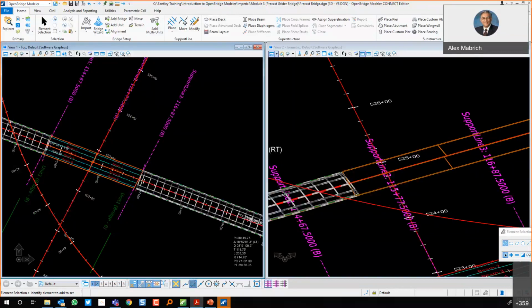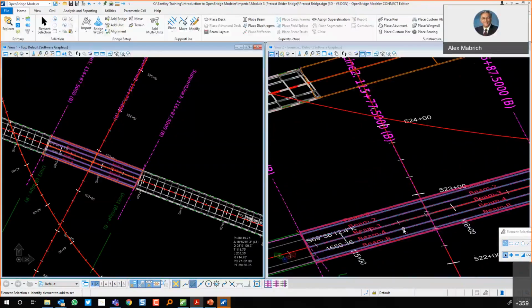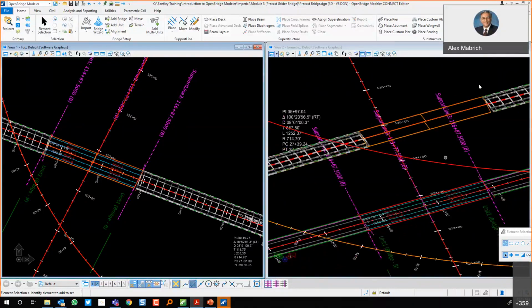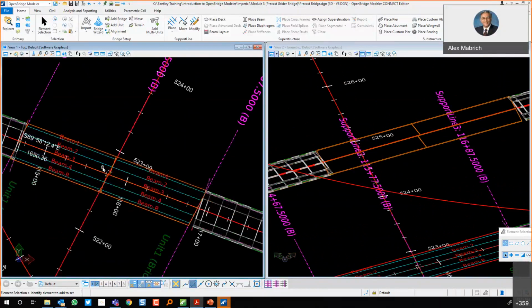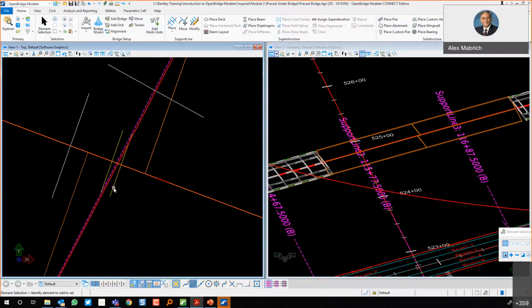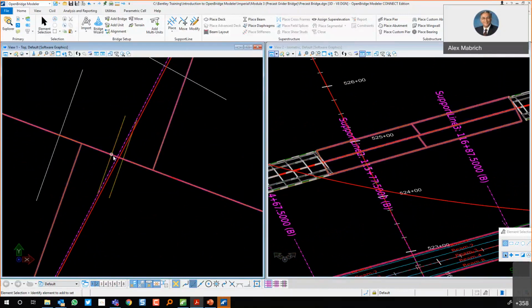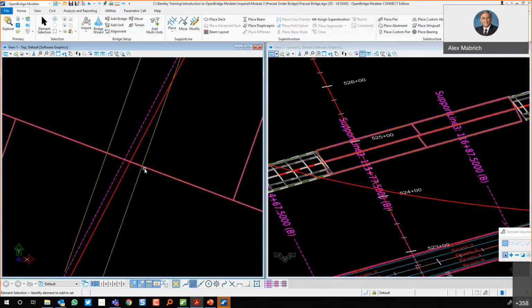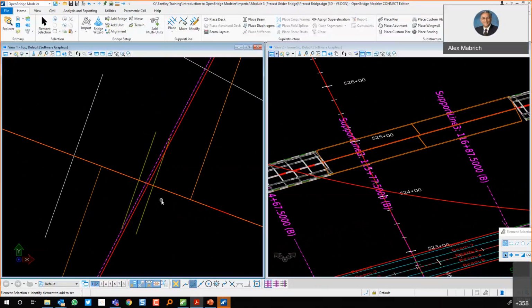Right? And then, these beam lines, we place not only in 3D, because we place it actually in 2D or elevation 0. Why? Because you can use it also to produce some plans there. Somebody said framing plans? Yes. Right? Now, what does it mean that SL offset that I just placed? If you take a look at the support very, very close, you see, this is where the beam is going to end, and this is where the beam is going to start. And that gap is 3 inches from here and 3 inches from here. That is the support line's SL offset that we're talking about, right?